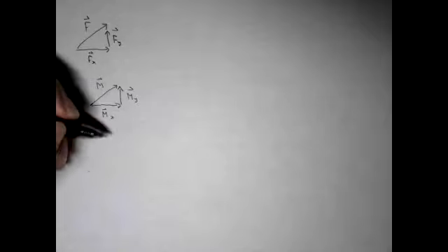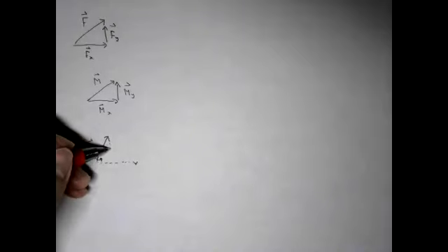Now, that being said, we can find the moment about a specified axis just like we would find a force about a specified axis. So let's think of it this way. If we have a moment vector, and remember that this magnitude simply represents a tendency for rotation. And I wanted to find the component of this moment along my unknown axis. I'm just going to call it V again. If I wanted to find the component of my moment along my V axis,